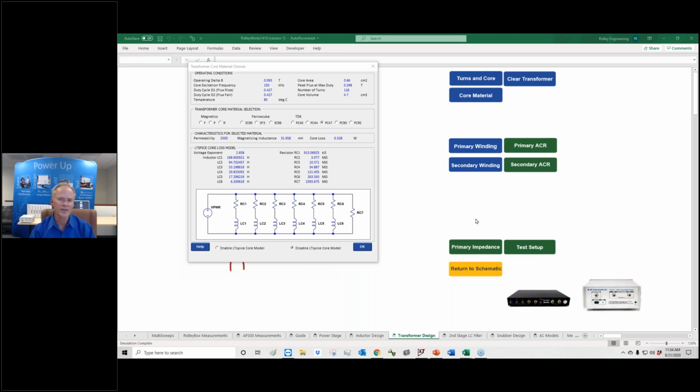The proximity loss doesn't care what's going on in the core. The results you get for analyzing proximity loss are independent of a core structure, unless you're creating a gap and putting a concentrated field into the windings, which you shouldn't be doing. So I'm not going to analyze a bad situation for you and put it in the software, because, as I said before, you shouldn't do the bad situation to start with.